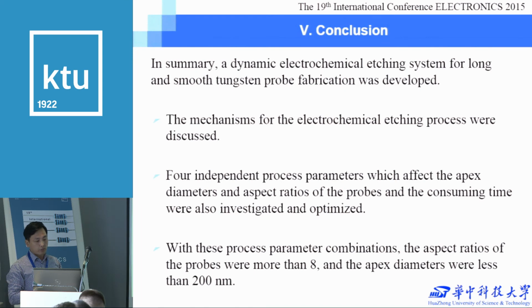With this process parameter combination, the aspect ratio of the probe was more than 8, and the apex diameter was less than 200 nanometers.